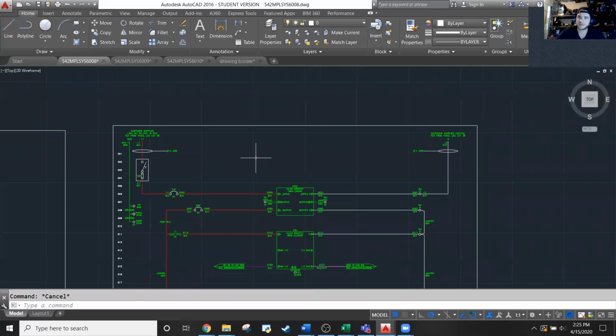We're just showing there's a neutral leg, and there's a live leg, and there's a ground leg. And it's all coming from customer supplied 120 volt AC, 20 amps with a ground, and then the feed panel location. And so for this particular drawing, this is for.